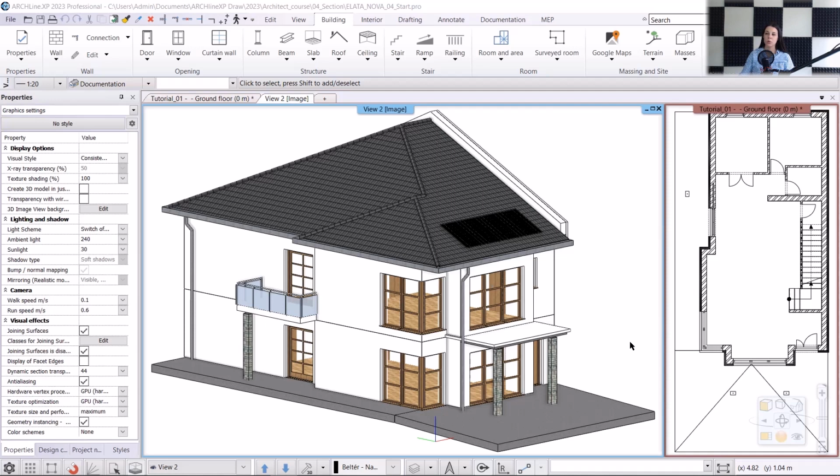It's useful to know that when creating the section line, it will automatically generate a name for it, and we can easily find it in the Project Navigator. For example, Section A, Section BB, and so on. Each section will have its own 3D view, avoiding multiple 3D views associated with a single section. If a 3D view associated with a section is turned off, a warning message will appear when trying to create a new 3D view for that section. We can check this in the Project Navigator.